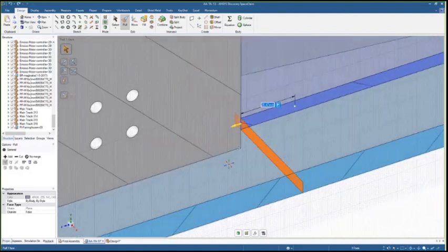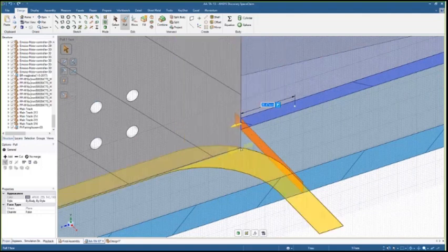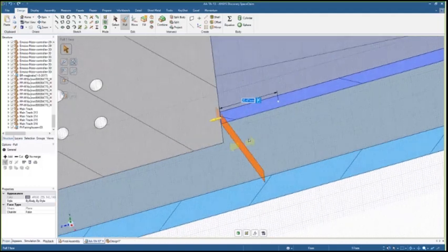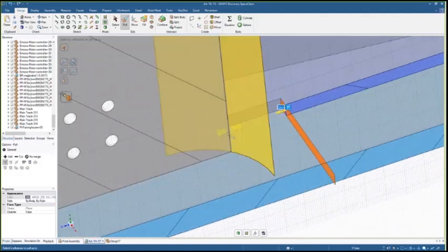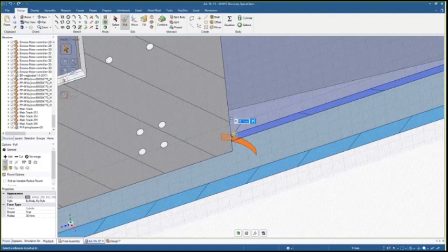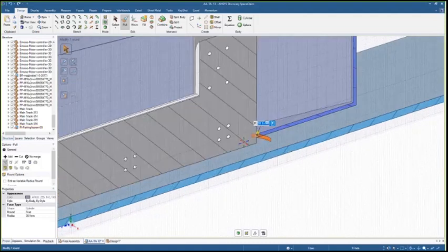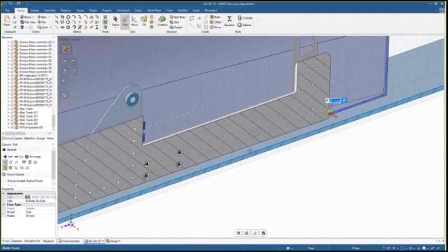So again, by interacting with the model differently, by pulling up to a face, it matches to that face. But if you pick just that point on the bottom here, it will just snap it to that point. So depending on what we want to do, we have a lot of different options. So pull is a great way to change the model and allow you to reuse something when you make changes.